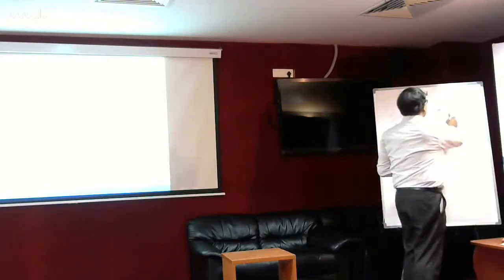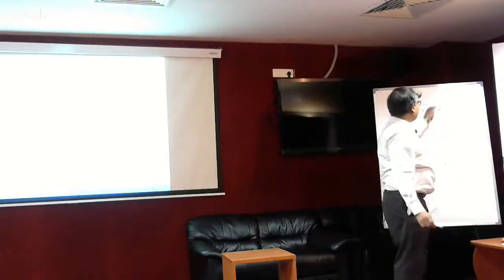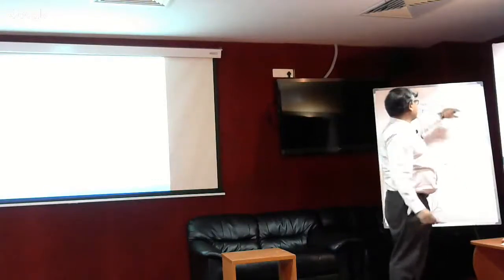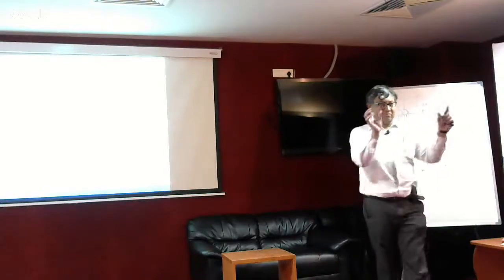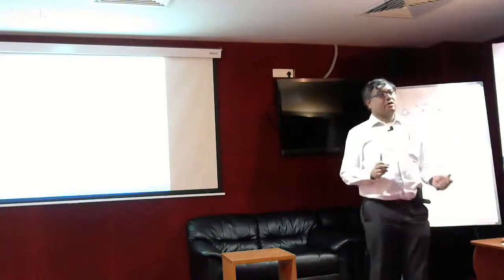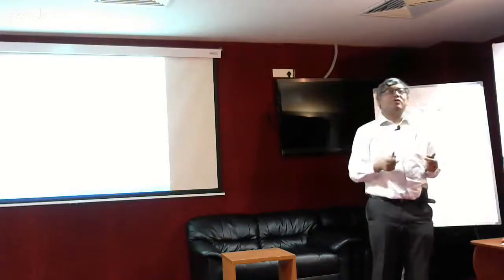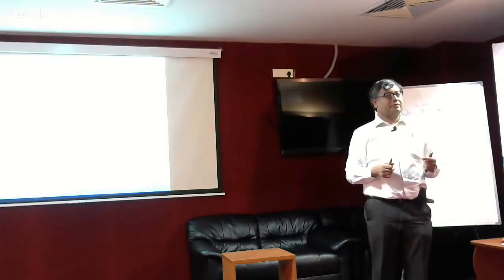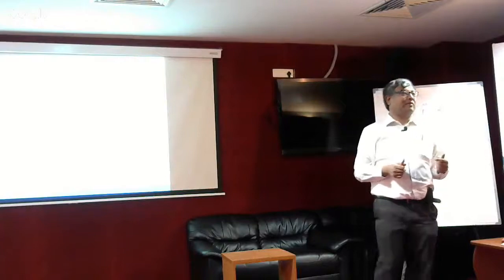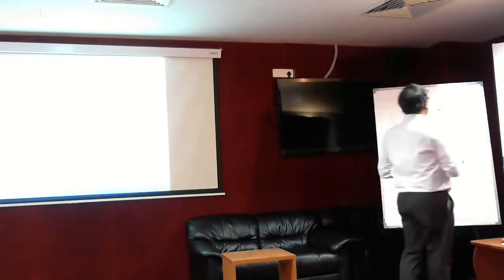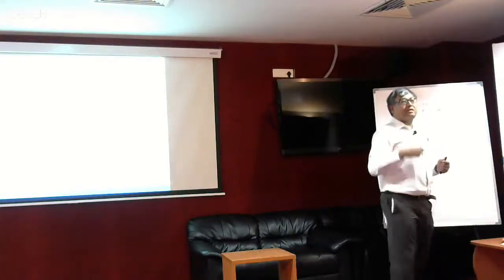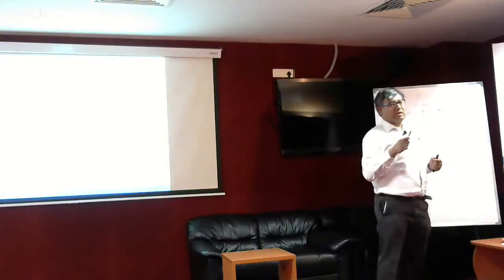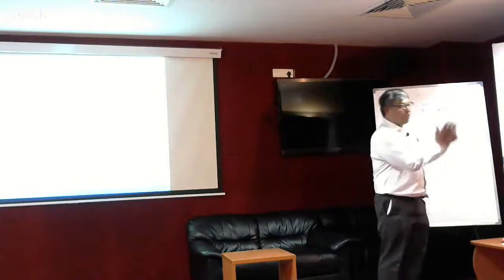So now, if this body is being acted upon by that force, obviously the flow is curved, but this body is not moving away because it's static in a particular position. There must be a counteracting force on the body as well, right? So effectively, the pressure difference is basically nullifying the centripetal force required to make the fluid flow in that curved form.